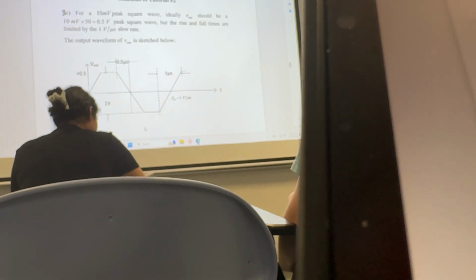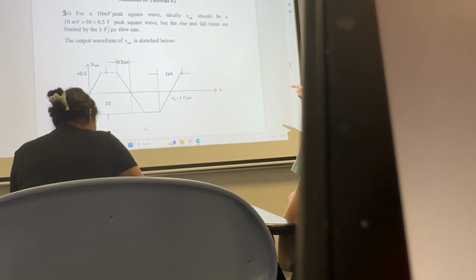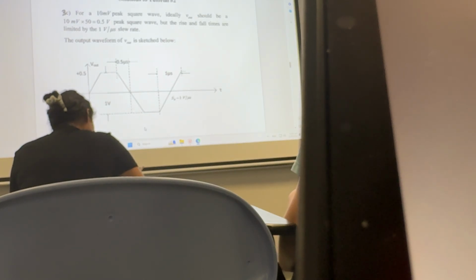You must have a distortion in this, there's no choice. A square wave cannot avoid it, right? Because the op amp has a limit on the slew rate, there will be a trapezoidal. From square to trapezoidal, from sine to triangle, from triangle also triangle but smaller in magnitude. This is slew rate distortion.